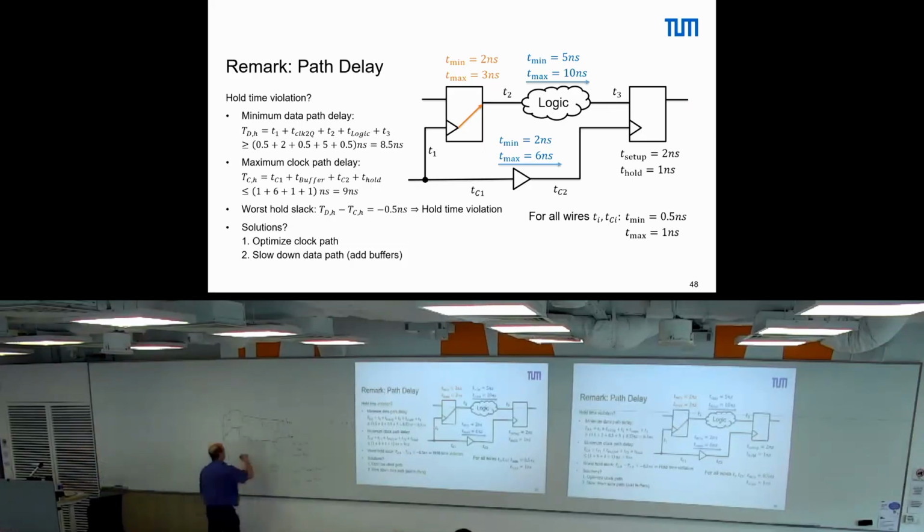So the only point where we could reasonably add one is actually here, right? Now by adding this register, we also changed our logic functionality. So we have to add a register here, and we have to add a register, maybe here. Then at the same clock cycle, we have the same logical result. We now need for the same logic functionality 2 clock cycles, right? Because we first need to process here, and then we need to process here.